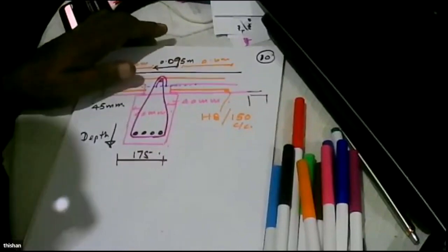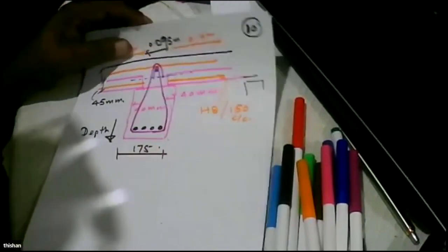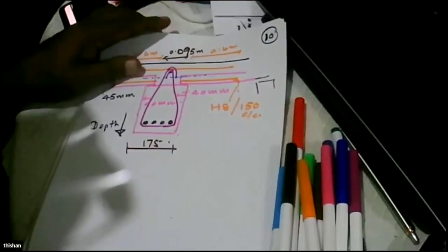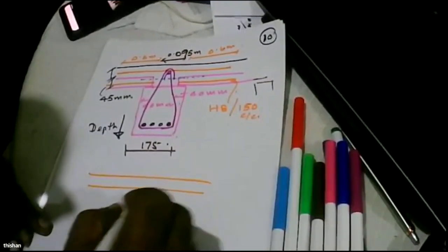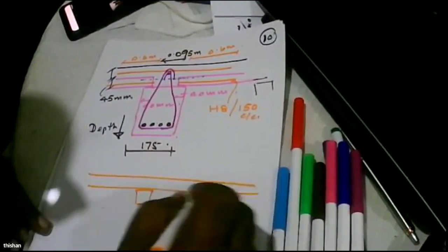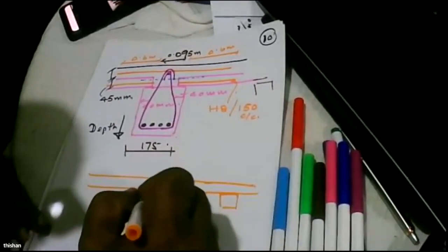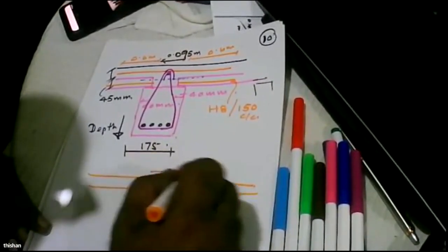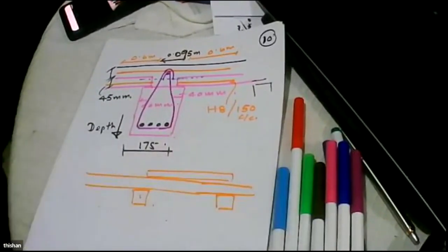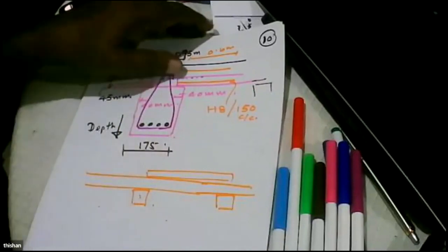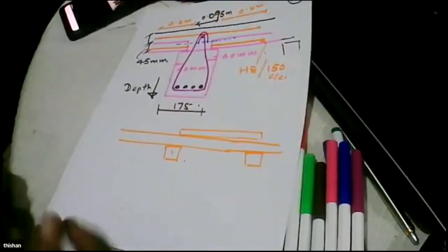There's a question. Is there any special slab arrangement under the partition walls, either in X or Y direction? Actually partition walls are not a problem at all. If you have a slab, beam, and another beam, and you are not sure of the slab capacity, the beam has to be designed for the partition load. We can have a small concrete lintel and do the partition. Then the loads will be transferred not onto the slab, but onto the beam.